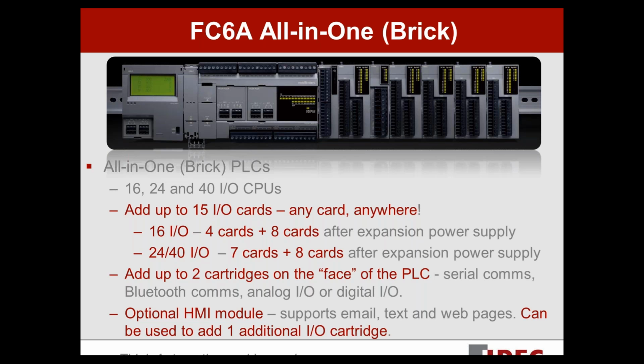The 24 and the 40 IO PLCs, you can have up to 7 IO cards before you need to add an expansion power supply. And then once you add that expansion power supply, you can have an additional 8 cards after that, for a total of up to 15 cards.